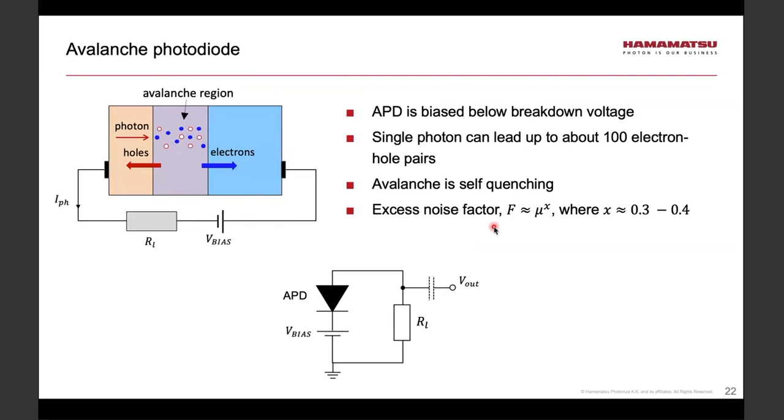I should have said earlier that in the case of a PMT, the excess noise actually diminishes with the gain. So there's the opposite behavior, and it's approximately given by the gain of the first dynode divided by that gain minus one, approximately.